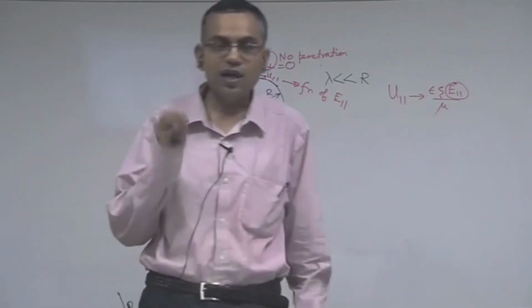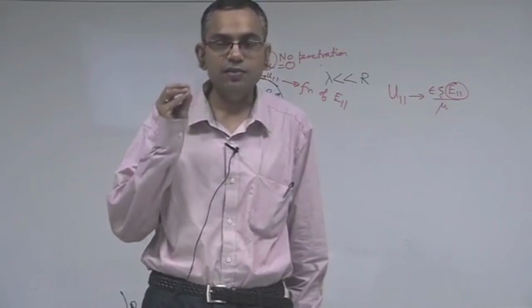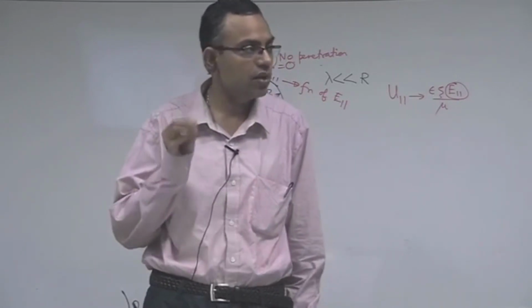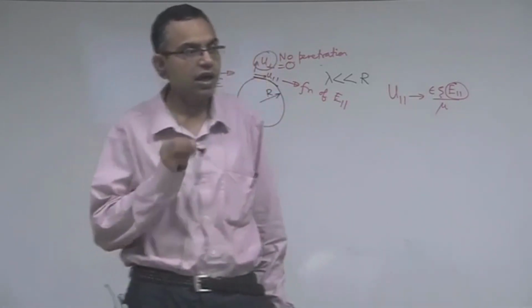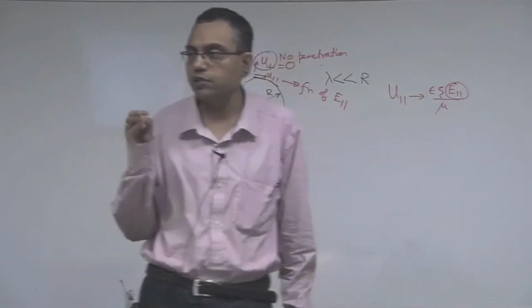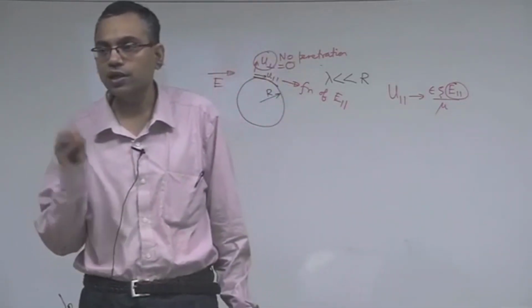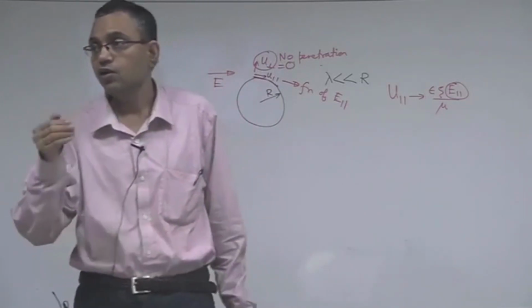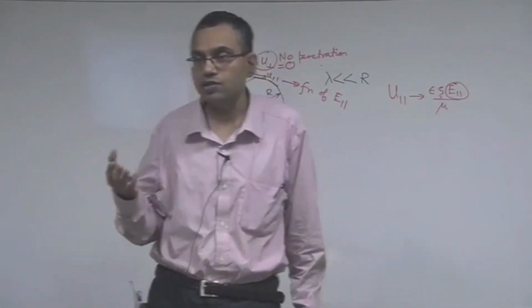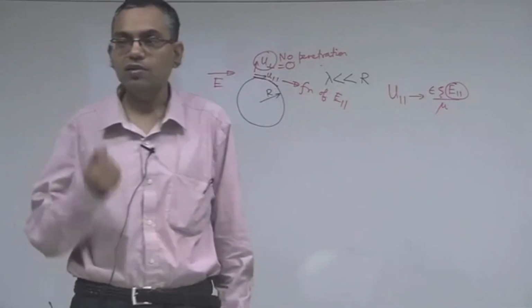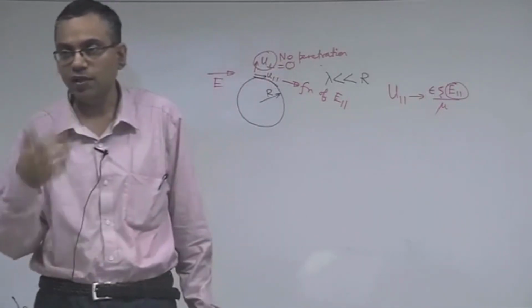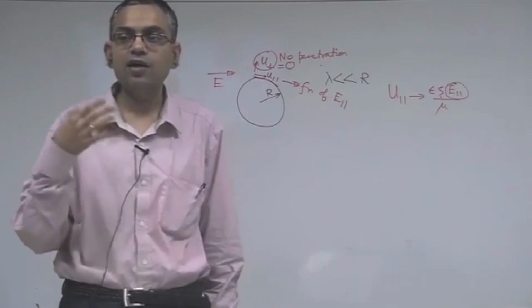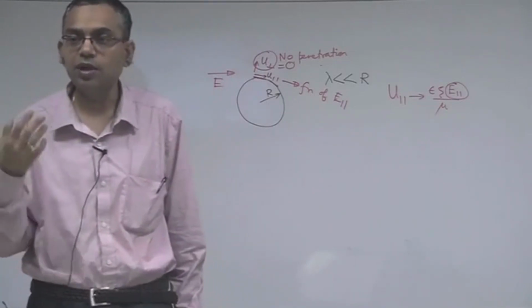The body force due to the Maxwell stress and the body force due to the osmotic pressure gradient together came out to be charge density times the external electric field, and when we plugged that into the Navier-Stokes equation and solved it, the velocity that came out was minus epsilon zeta E external by mu.